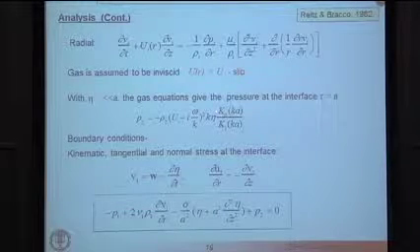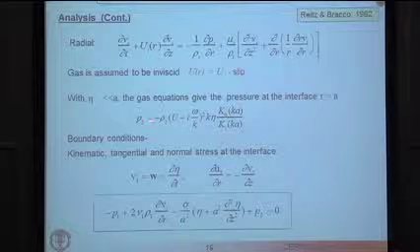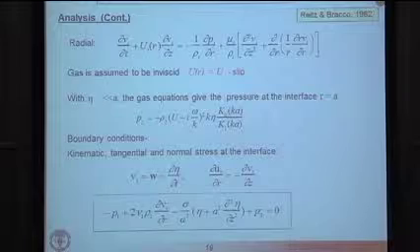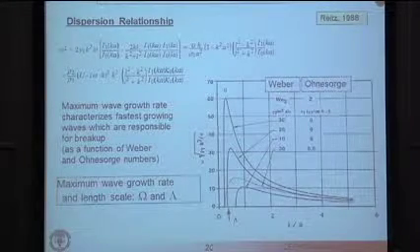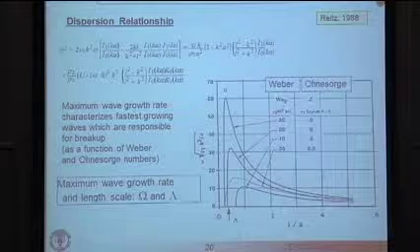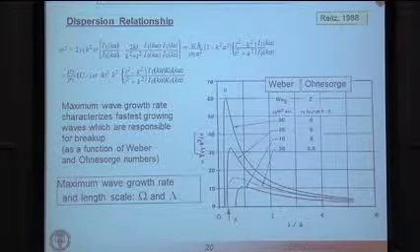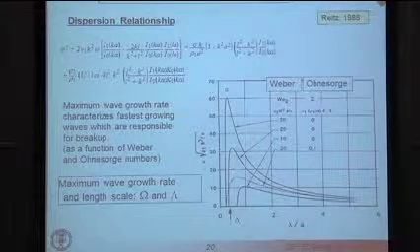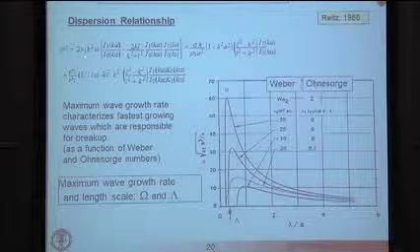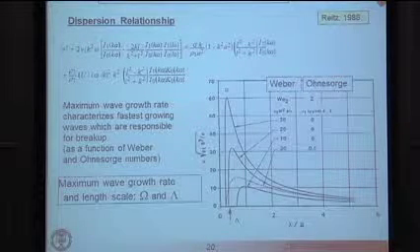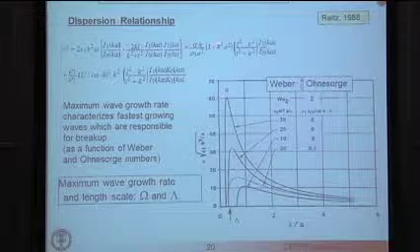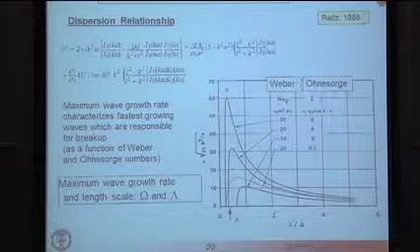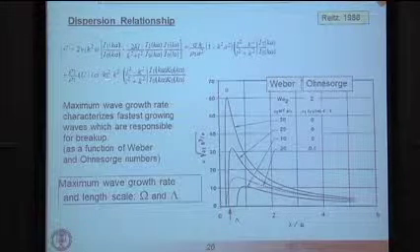So when one plugs this expression here for the surface pressure in the gas phase into this result and then applies these boundary conditions, you come up with what's called the dispersion relationship. A very complex looking equation here that relates omega, the growth rate of the waves, to their wavelengths, k, or wave numbers. It involves Bessel functions. Here you see the liquid viscosity term, that's kind of a damping term. Here you see the surface tension term. And then here you see essentially the forcing function, which is the gas density over the liquid density ratio times the dynamic pressure term, U squared.